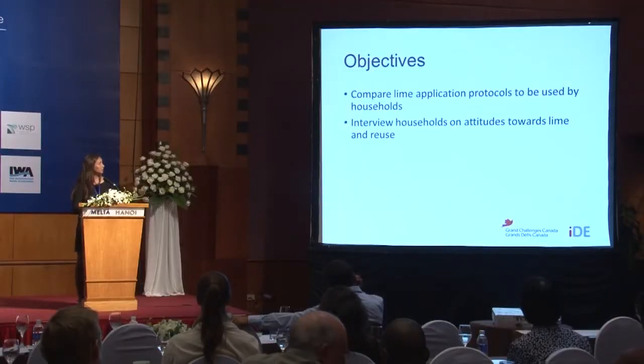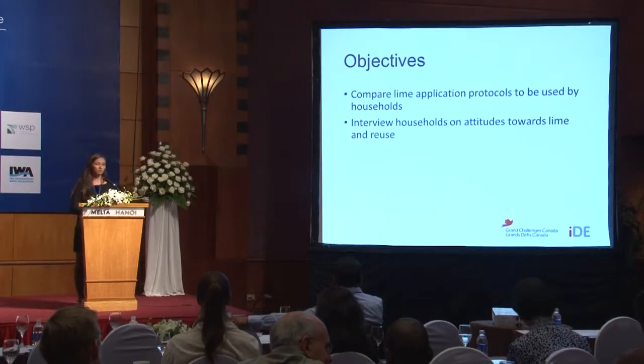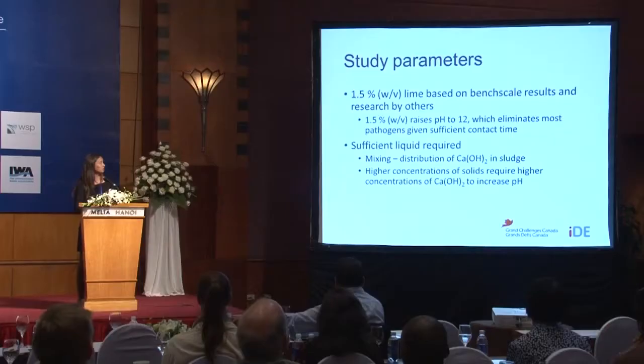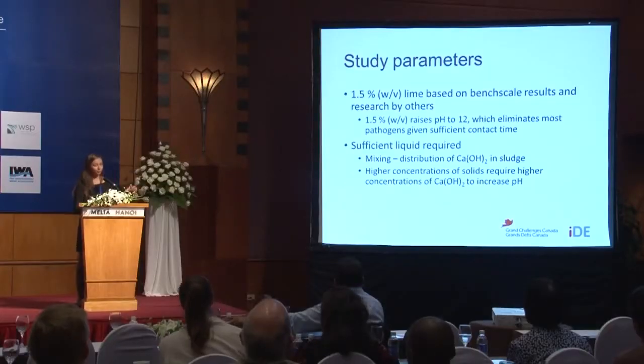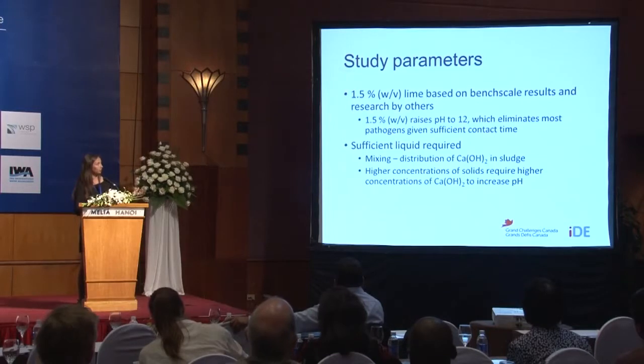So for the household tests, here's some information on that. We wanted to compare a few different lime application protocols to be used by households, and also interview households on their attitudes toward lime and waste reuse. Basically based on the bench scale results, we had a value of about 1.5% weight per volume of the lime to use. So volume waste, weight of the mass of lime per volume of waste.